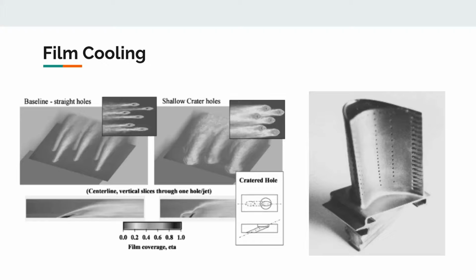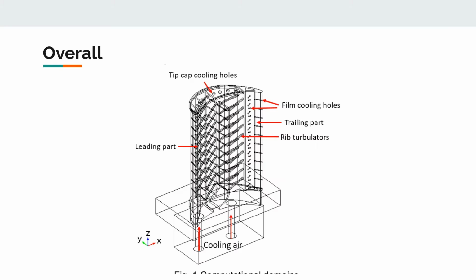Much of the design of film cooling is concerned with hole entry, hole shaping, orientation, spacing, momentum flux ratio, effects of mainstream turbulence intensity, external surface curvature, and external surface roughness. As you can see on the picture to the left, the experiment illustrates how different geometries generate different film properties. On the right, you can observe the holes that allow the cool air out and form the film.